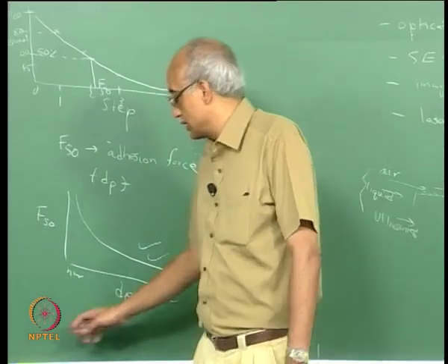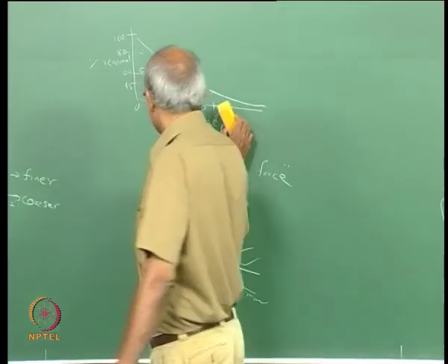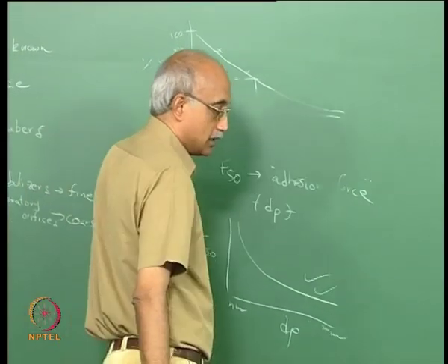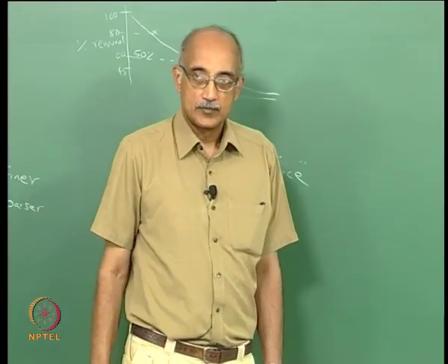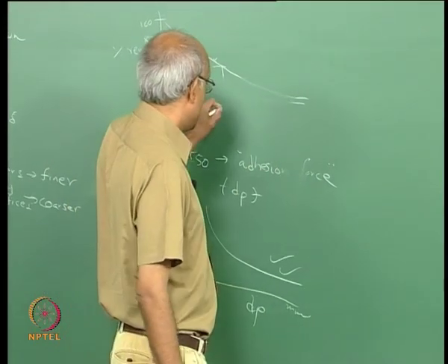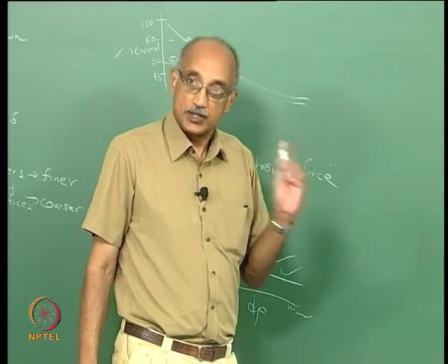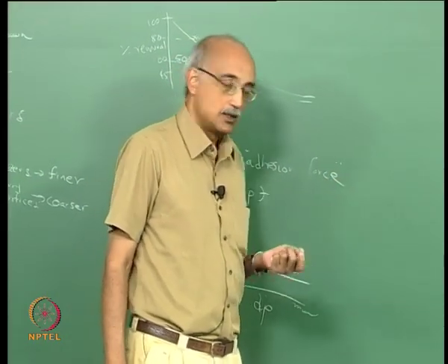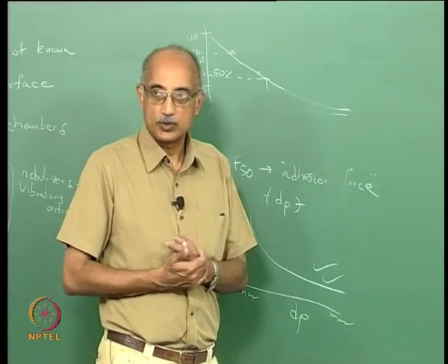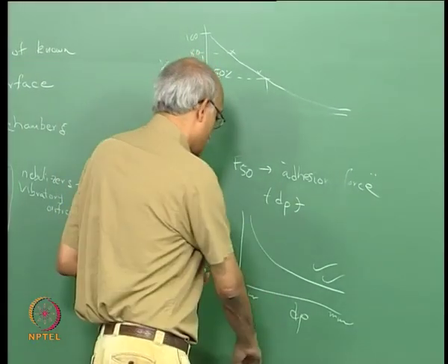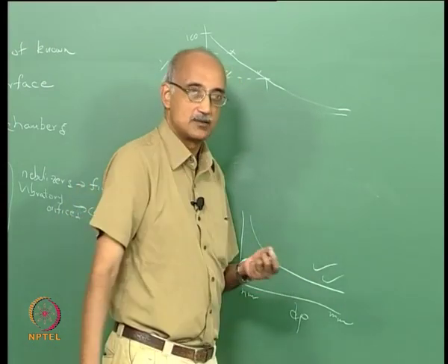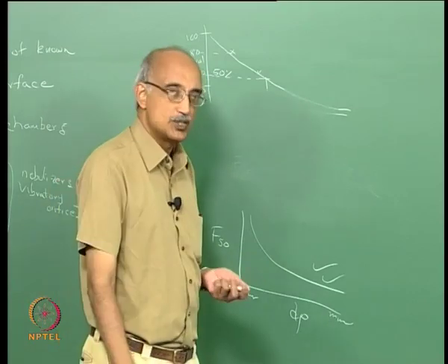For example, when I take this duster and remove the chalk writing from the blackboard, that is a dry cleaning process, right, because the particles from the chalk have been transported and they are adhering to this blackboard, and when I just use a wiper, all I am doing is applying a dry force to remove the particles from a surface. As you can easily see, dry removal is never 100%, right. It's not a very efficient process.